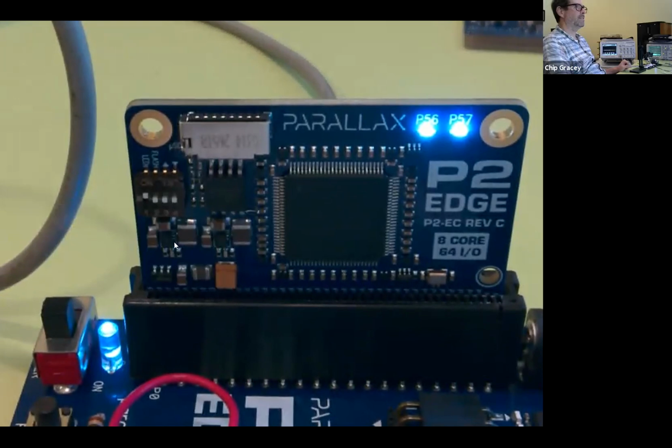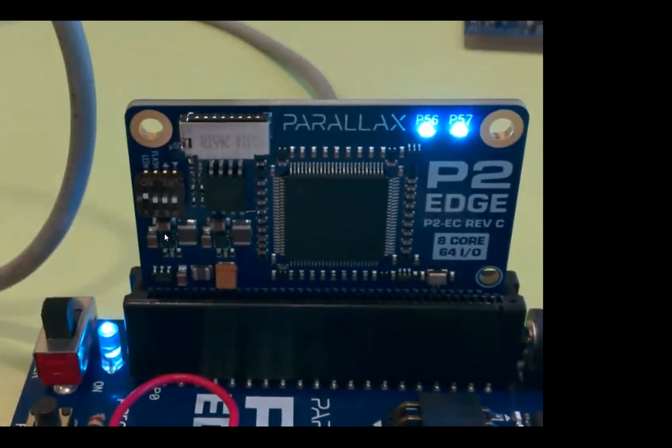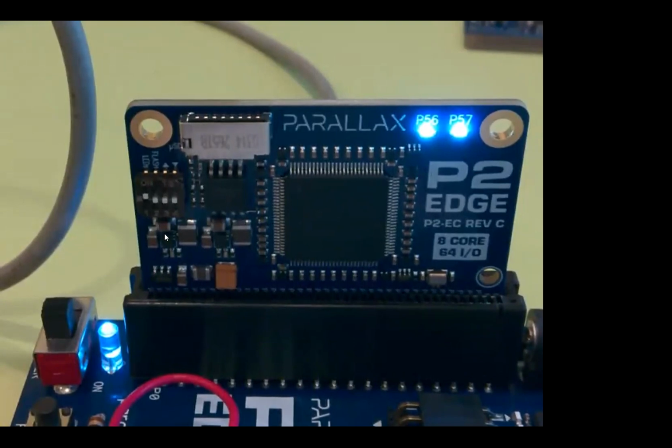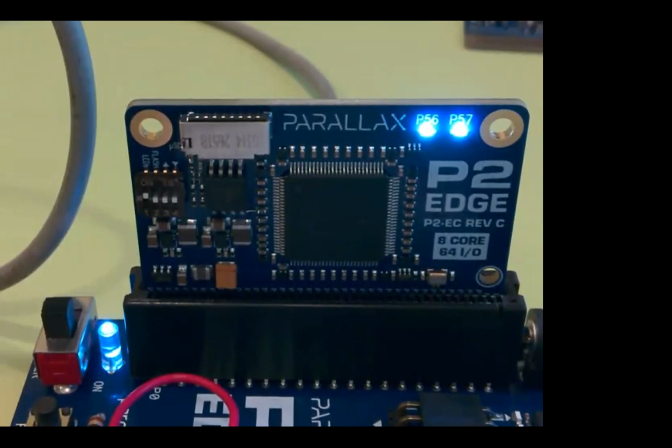It comes down to these chips. You can get to 60 volts when you jump start. Right, the load dump on a car can go to 60 volts. I think for a car, you'd put some kind of protection circuit in front of something like this. Yes, you sure need it.